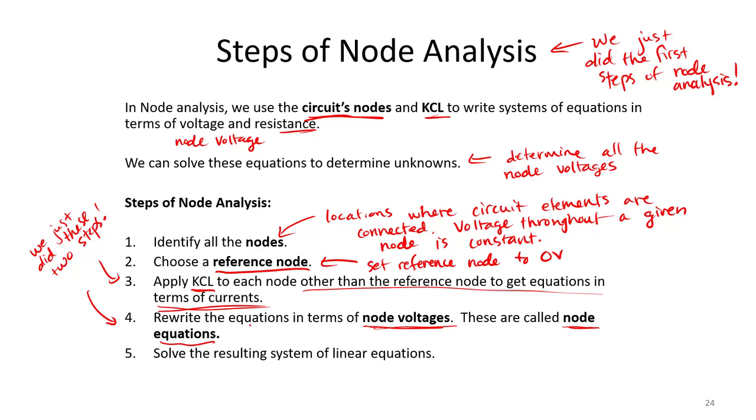You will end up with one node equation for each node. And so at the end of the day, all you need to do is solve the node equations simultaneously in order to find the unknown voltages. So if you have 2 unknown node voltages, you would end up with 2 equations and 2 unknowns. You solve them and you determine the final values of those nodes.